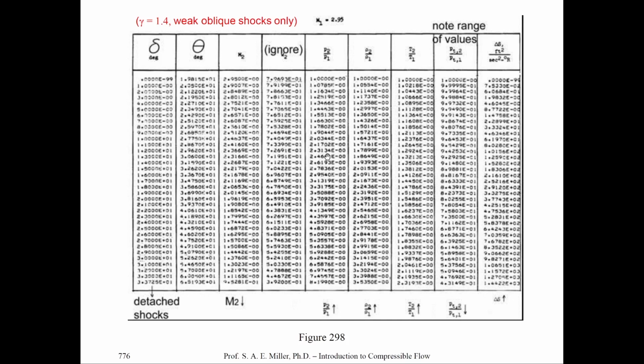And of course, all the pressure, density, and temperature rises will rise across the shock, as you see from decreasing and increasing wave angle values. And of course, you'll see that our total pressure goes down in the tables for each corresponding row, and we have an increasing delta S. And I've denoted these relations at the bottom of the figure, courtesy of Professor Gary Settles, actually.